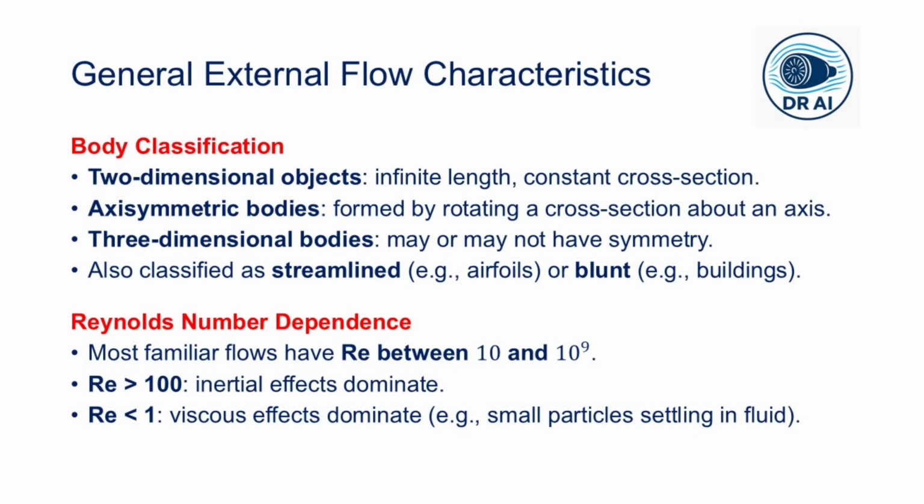The average pressure on the rear becomes much lower than on the front, creating the pressure drag, even though the viscous shear stress itself might be tiny. So this explains D'Alembert's paradox: inviscid theory predicts zero drag, but real fluids, no matter how small the viscosity is, will produce a drag because of the boundary layer separation.